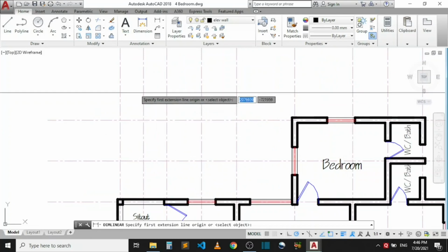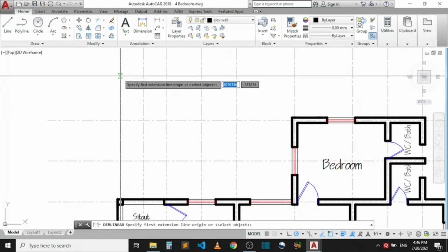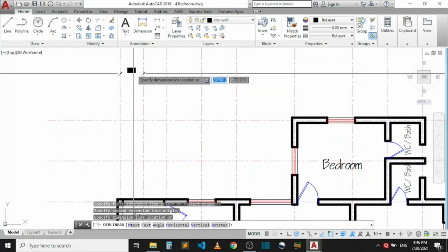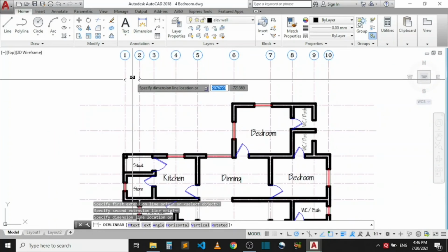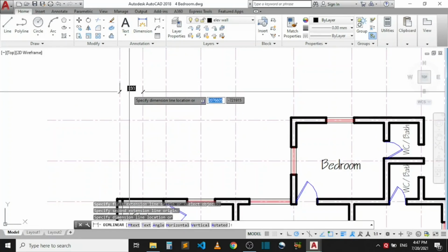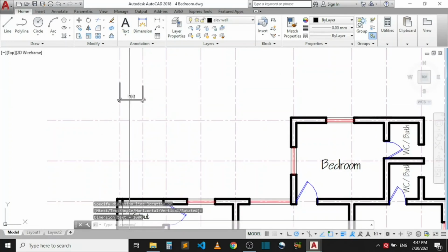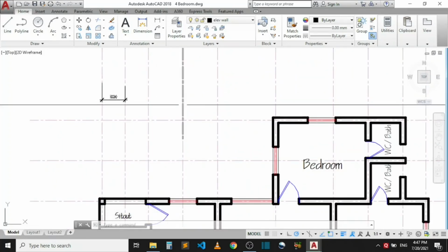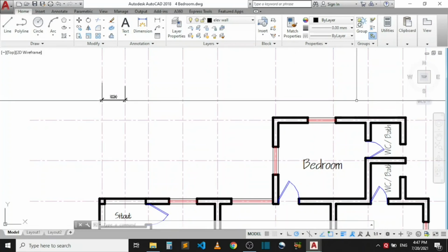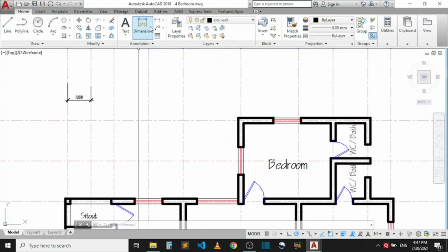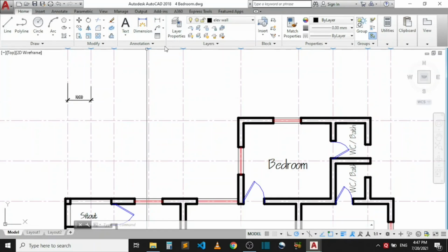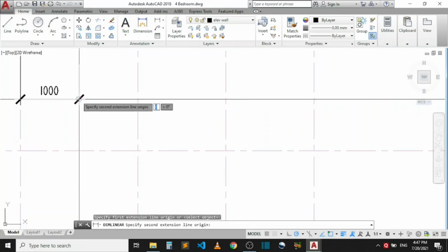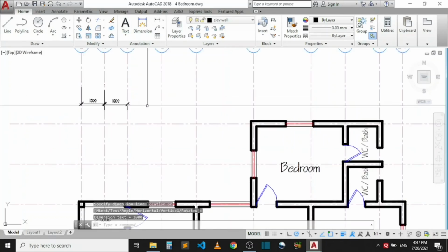To start drawing the first dimension, I'll click here, move to the next point, I'll click, then I can move away, or simply wherever it is I can place it if the distance is okay. But let me bring it down a bit to this point. I'll not click it. Now what happens if I want to draw another dimension here, and at this point, and at this point, and at this point, like this, right up to the end? Will I keep going back and forth, picking my dimension command, like coming here again, clicking here like this, and placing it like that up to this place?